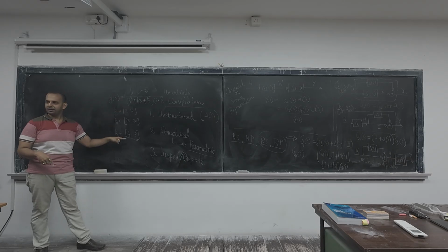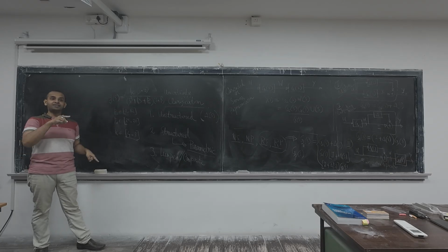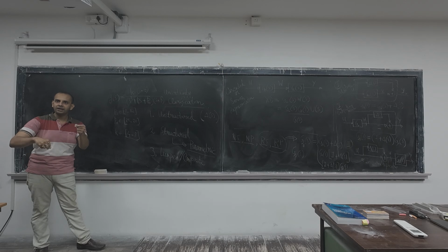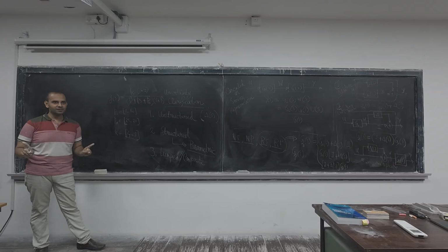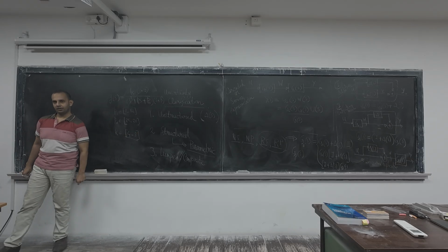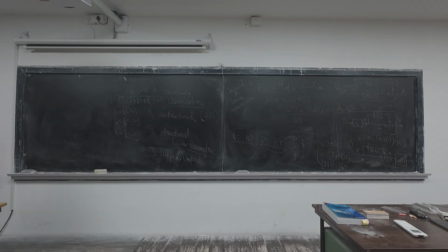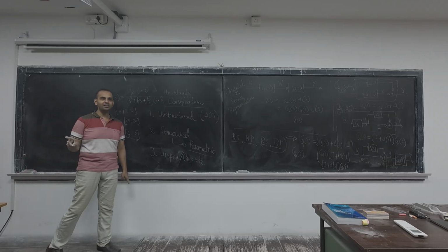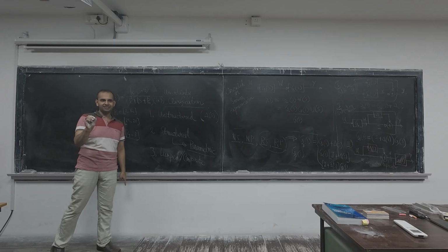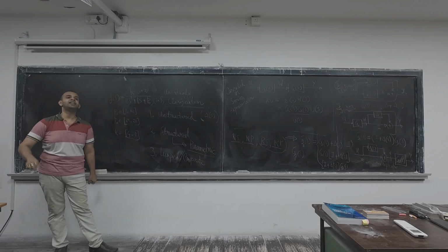So even if all three change simultaneously, is there any possibility that a new pole or zero will come in, or an existing pole or zero will go off? It is not. That's why it is called a structured uncertainty. The structure which was originally there, that we know, and there is no change in the structure provided there is any bounded variation in the parameters.